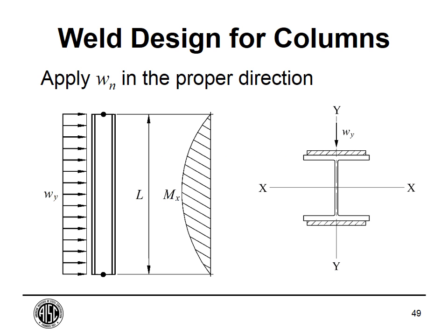Now, one thing I will mention is that the direct analysis method spelled out in the specification uses point loads, concentrated loads, instead of a uniform load like I've got shown here. The reason I use a uniform load is because it gives us really what the direct analysis method is looking for, which is to get the same moment.